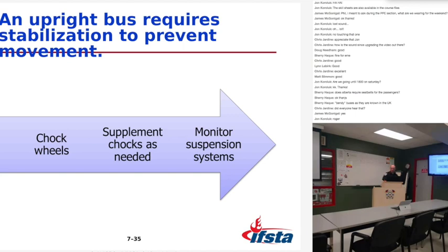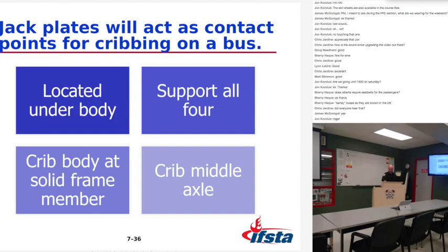Common suspension systems are leaf and coil or spring, and air suspension. The chassis could drop without warning if the air pressure was lost. Do not use the air inlet valve to reinflate. Mechanical suspension, treat as air suspension.